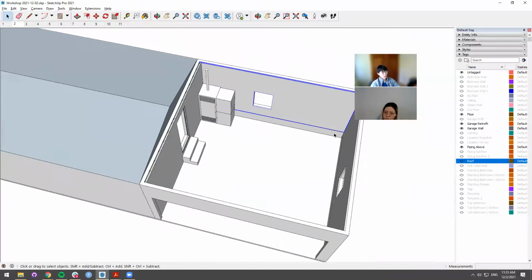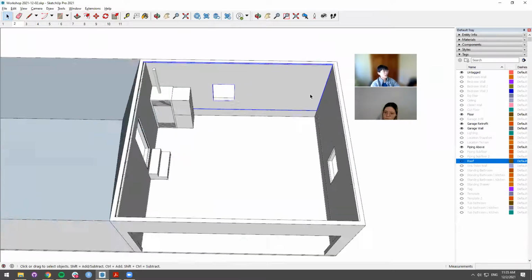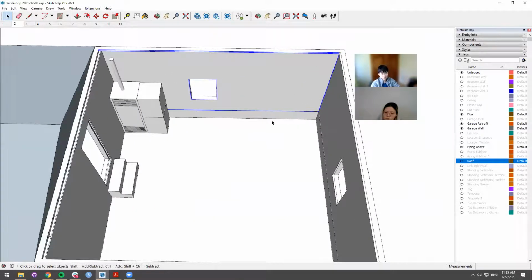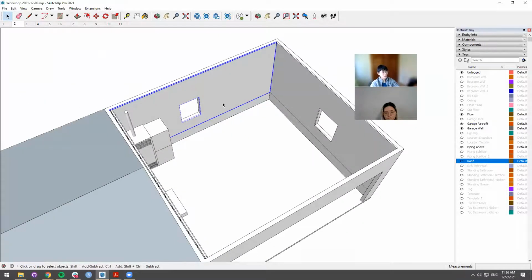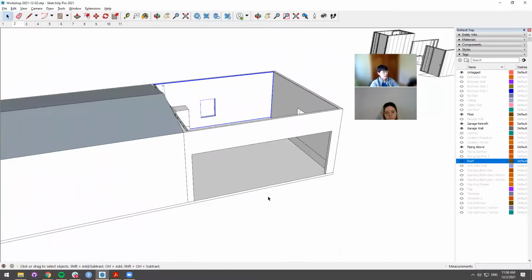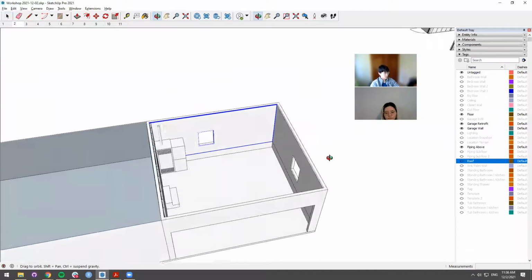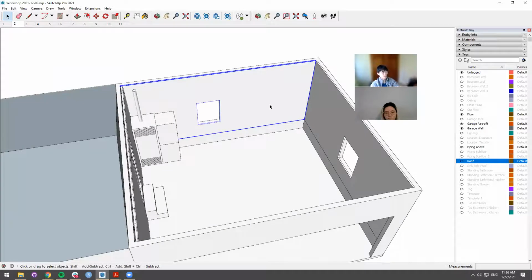And then on the other walls, they may not need to be thickened in any way, but because in this instance, and it might be true for many other garages, there was a concrete curb that was sticking out, then imagine furring is the kind of approach for these other walls. After you've added the necessary insulation, once you've done the necessary wiring inside the exterior walls, then you can apply drywall, maybe not do the final patching and painting, but have that all kind of ready to go before you've done anything that's prefab related. If you needed new windows, you would do it at that time, and you wouldn't necessarily do anything yet to the ground. So that's step one, this kind of presenting the blank canvas.